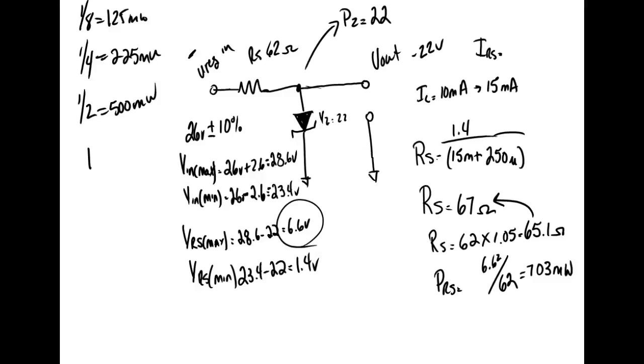So if I come up and I get negative watts, is there such a thing as negative watts? So yeah, Brandon, if we use negative 22 volts to calculate our power, because it's dropping 22 volts, you understand? It doesn't make any difference if it's negative or positive, it's dropping 22 volts. So when I calculate my current through my resistor, am I going to use negative voltages? No, I'm going to use absolute values, right?